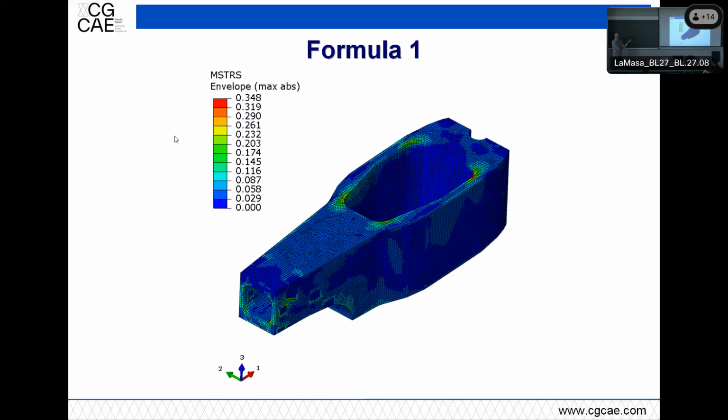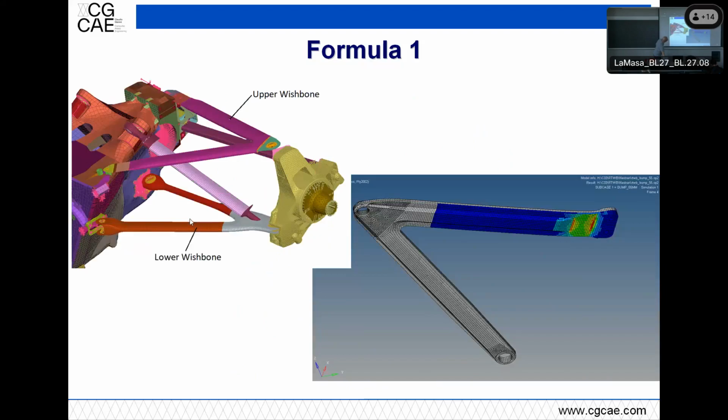Carbon as well is a problem, because carbon fails, but you can somehow more easily repair it by adding plies again, cutting out the portion which is damaged, and substituting. Not a nice thing to do, but it's still possible. So this would be something interesting in the future, to see if some teams might decide to go for this approach.